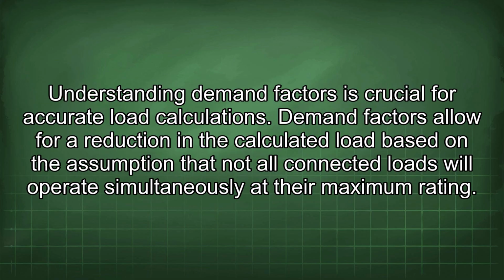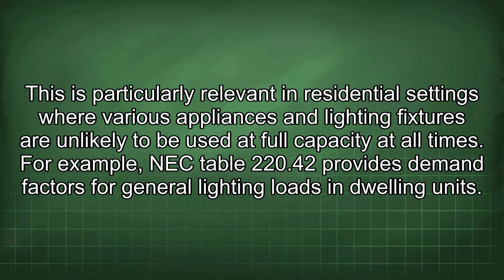Understanding demand factors is crucial for accurate load calculations. Demand factors allow for a reduction in the calculated load based on the assumption that not all connected loads will operate simultaneously at their maximum rating. This is particularly relevant in residential settings where various appliances and lighting fixtures are unlikely to be used at full capacity at all times. For example, NEC Table 220.42 provides demand factors for general lighting loads in dwelling units.